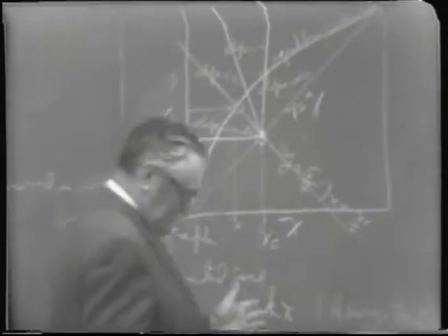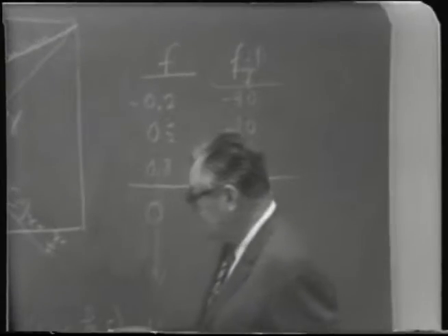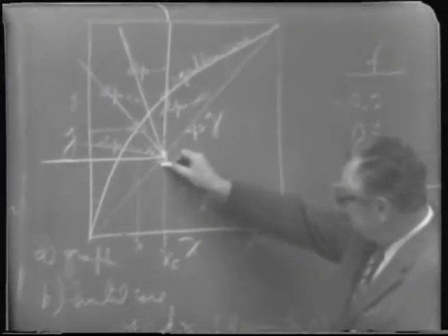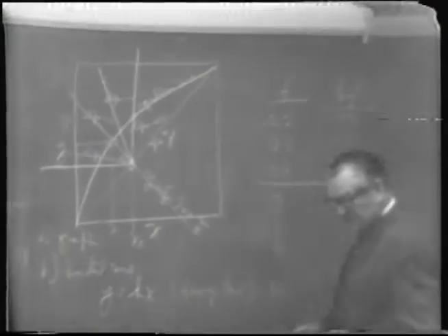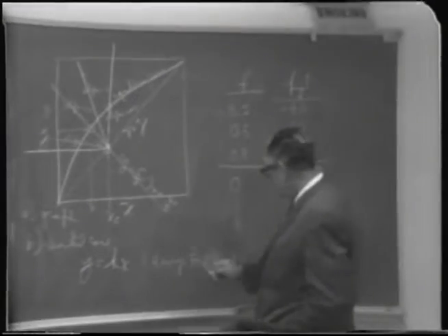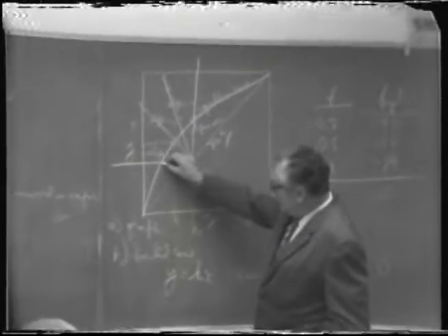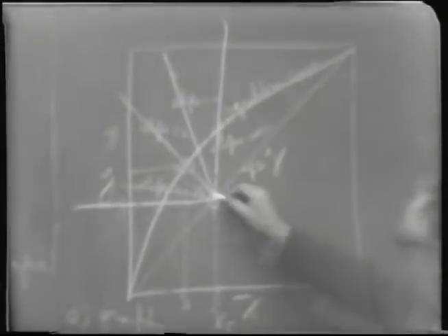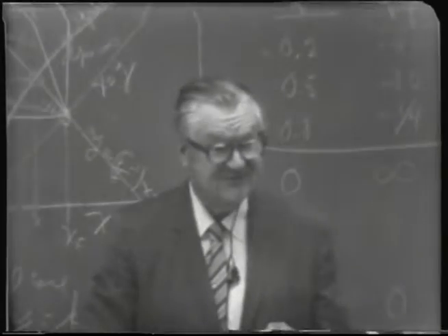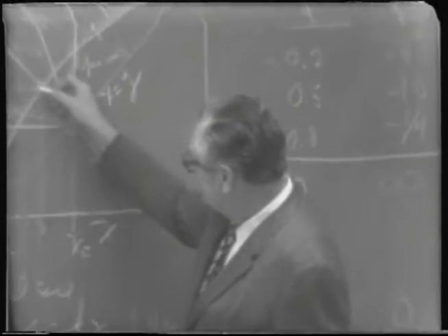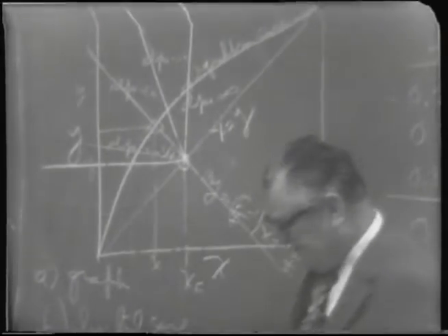Similarly, as you approach 100% vaporized, where the slope is 0, then the composition of the vapor approaches this value here. In other words, essentially what's in the feed would be in the vapor. But if there was a little bit of residual liquid, it would simply be this value here, wherever it intersects the curve.